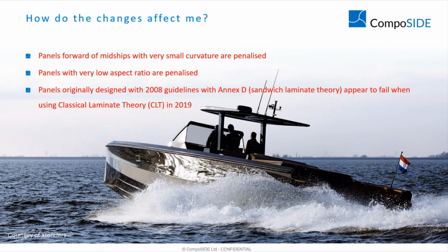The importance of the material database to prevent unrealistic failure modes, and how this is linked to the theory used. It is worth noting that the use of classical laminate theory is a correct approach when analyzing complex layups, including asymmetrical layups, as this is nearly always the case for hull laminates.